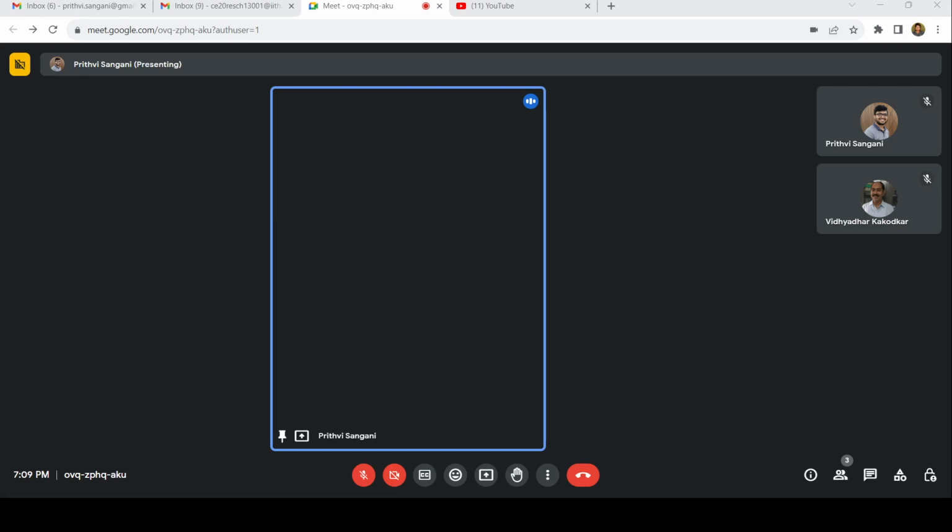So we have member, length of the member, Fi, internal forces due to the externally applied loads, and we have ui, the internal forces due to applied unit virtual load, and we have fi ui li, and we also need to take ui square li.